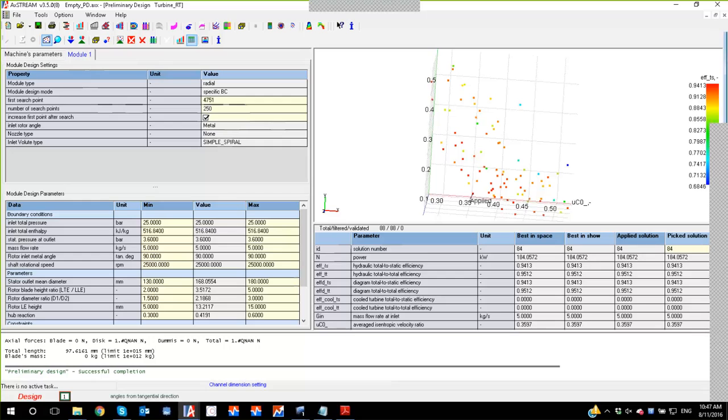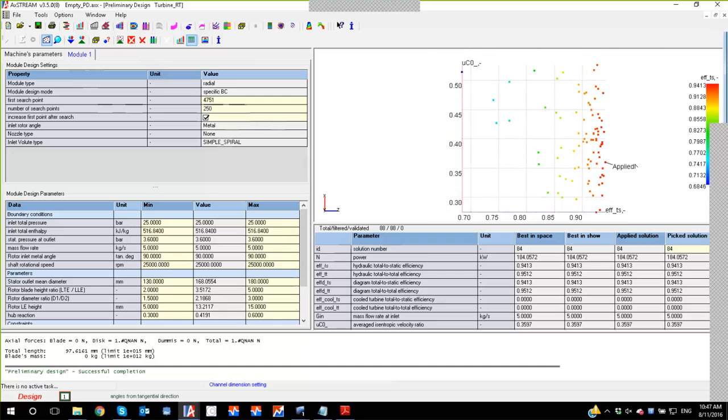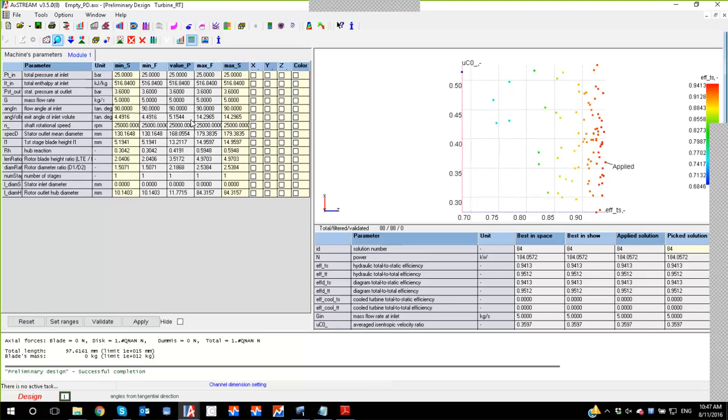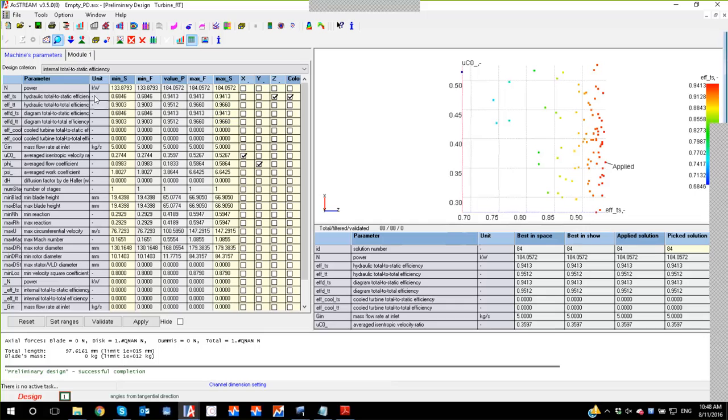different radial turbine geometry. So in order to not have to click on each point manually to see which one we like and which one we don't like, we have a tool that's called the Design Space Explorer, in which we're going to have quite a number of properties that can be used to display on any of these axes for the graph here. For example, here I can look at efficiency on the z-axis, and as the color here as a function of the maximum Mach number.